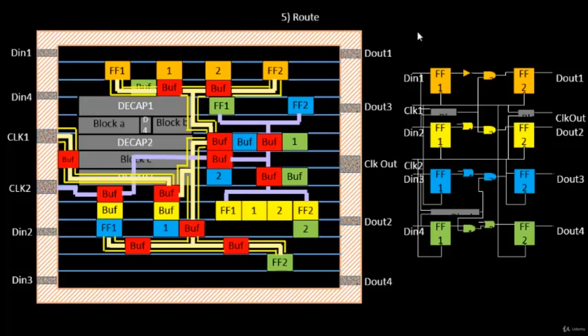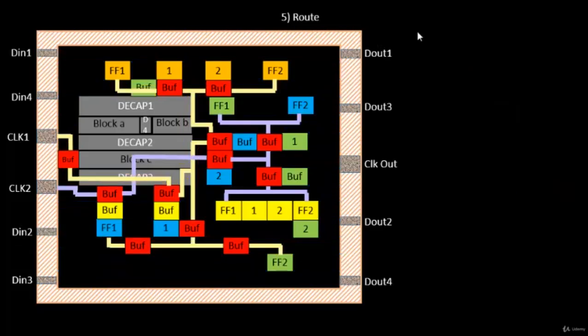There are various algorithms that have been developed over time, and we are going to look into one such algorithm. Let's remove the netlist and the power lines from here, and look into one such algorithm, which is called maze routing, or Lee's algorithm. Lee is a very famous person who invented this maze routing concept, though it has some limitations, but he was the first one to come up with algorithms of routing.